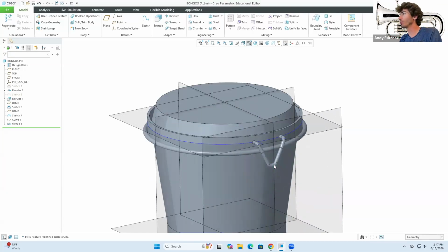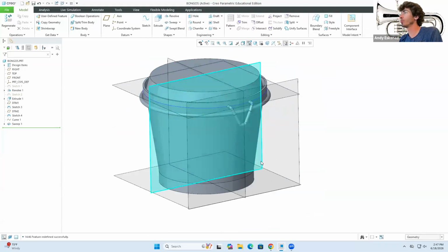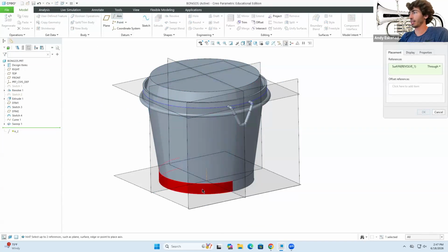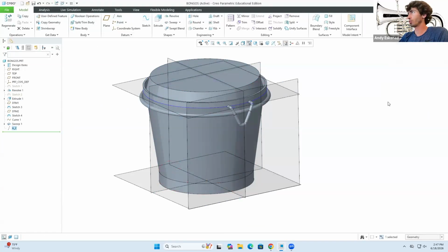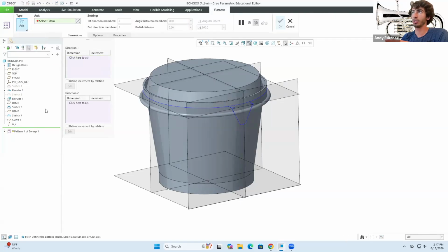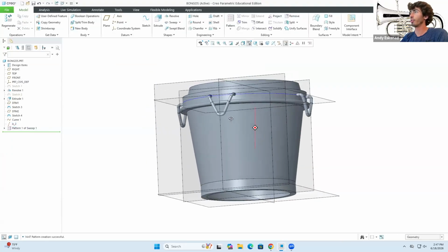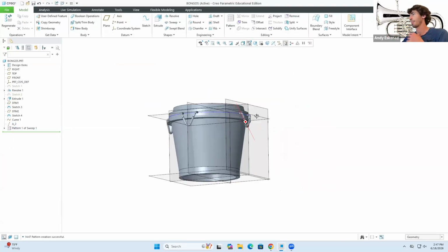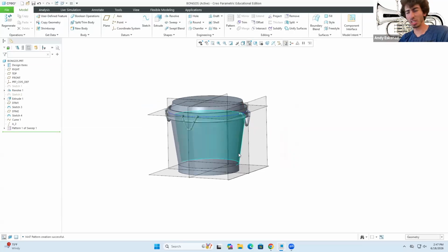Then what we could already start to do is we can go here to axis, and I'm gonna bring an axis that will be right there. Actually, in fact, I might need to bring it before anything else. So we could click on sweep one, go to pattern, and then go here to where it says axis. So we'll revolve it around there, and I can say 4, yes. So it should generate 4 of these. So you see, at least that seems to be nicely done in there.